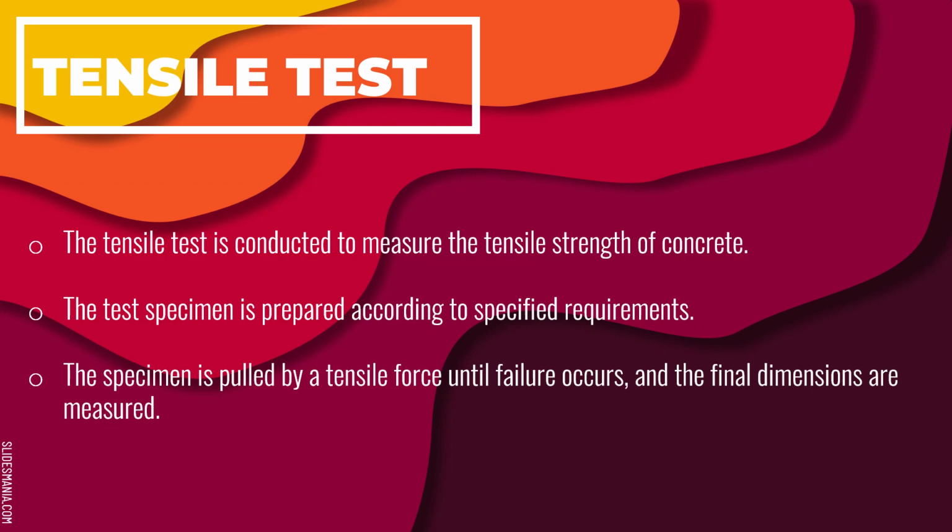Lastly, tensile test. The test specimen must comply with the stated requirements, which are the shape of the test specimen, material, and allowable dimension. Next, the initial dimension is measured. After that, the tensile test apparatus is set up. Then, the loading shaft is extended slowly by using the handle.